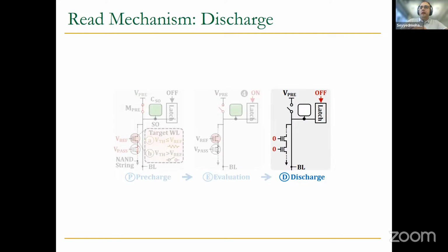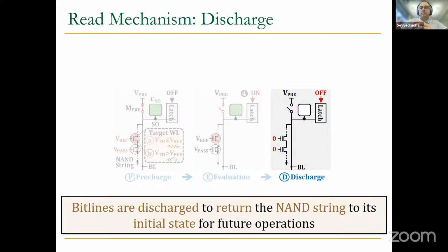And after evaluation, you need to discharge. For discharge, your bit lines are discharged to return the NAND string to its initial state for future operation. And you need to turn off the latching circuitry.